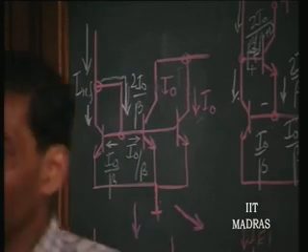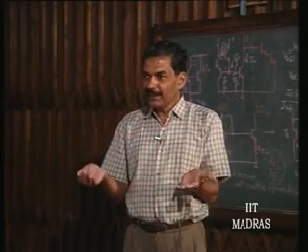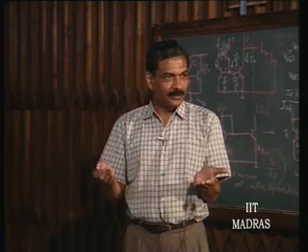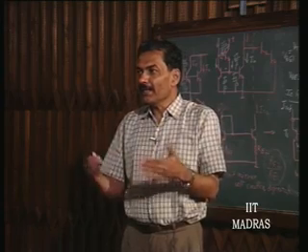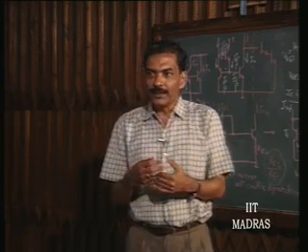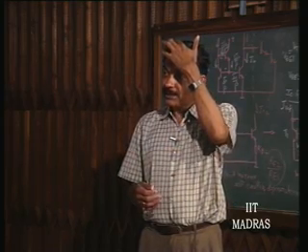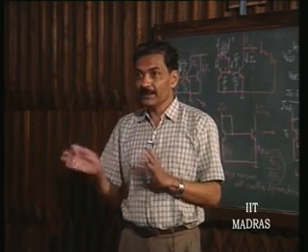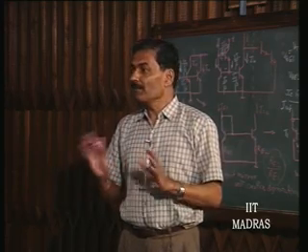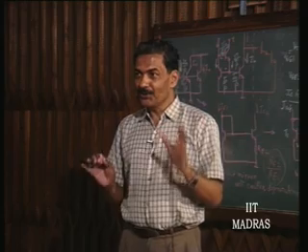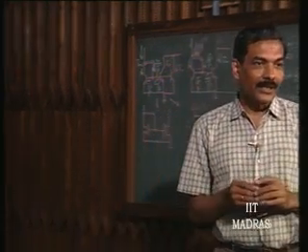That means the area of the transistor is what? Double the original area if 2 transistors are connected. If 3 transistors are connected, triple, like that. Therefore, by multiplying the area, you can generate currents which are going to be a ratio of areas. Is this clear now? It is not necessary to have integral multiples. The ratios can be shown to be a ratio of areas, and you can have the current as a ratio.